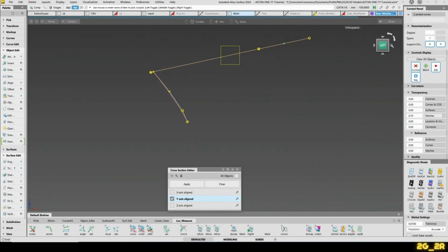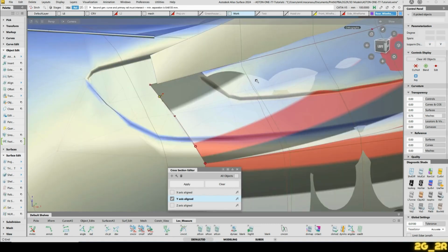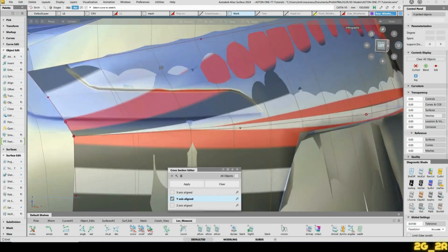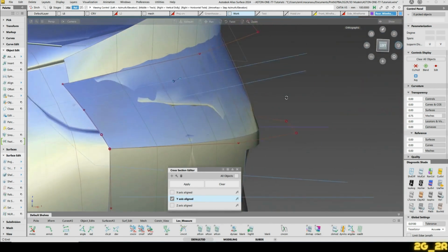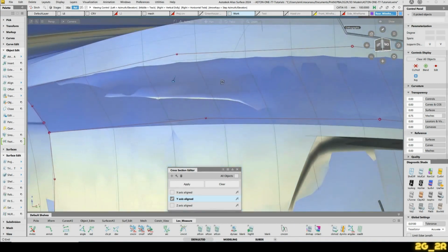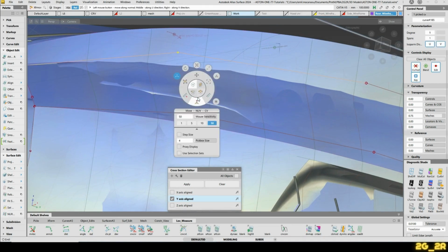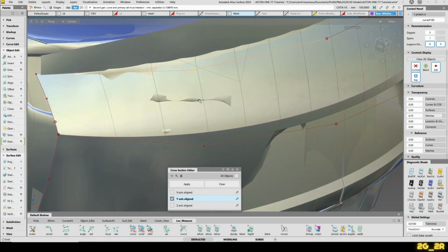We'll add CV normal to this curve, to this normal direction. I'll extend this because that moves it off of the X direction that we want in this curve. And now let's roll this that way. Just bring us closer here.